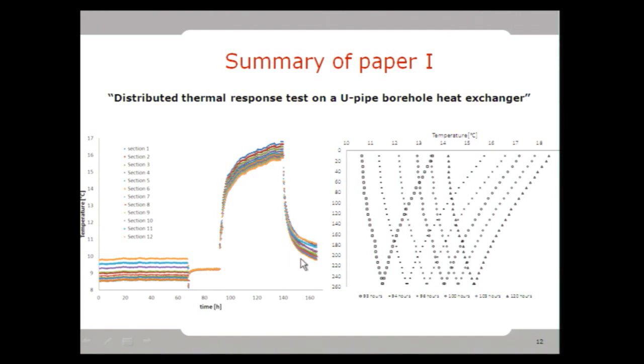And as I said, the thermal recovery period is used for the determination of the ground thermal conductivity, and the heat injection for the determination of borehole resistance. If we want to see each of these periods in time along the depth, I'm illustrating several instances in the chart to your right-hand side, where you can see the temperature profile along the depth at different moments.